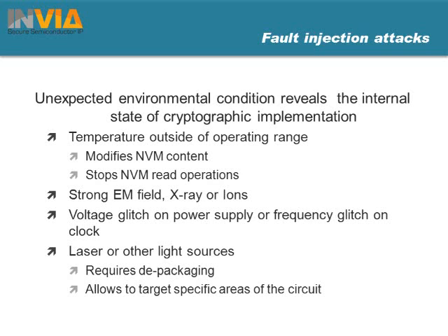Strong electromagnetic fields, X-ray or ion. That is well known to people designing for airplane or satellite electronics. These people try to avoid as much as possible what is called SEU, single event upset, or SET, single event transient, which is basically a neutron flipping a bit somewhere in the chip. Well, the attacker would do exactly that. He will try to flip a bit somewhere in the chip, and he'll hope that this flipped bit propagates through part of the design.